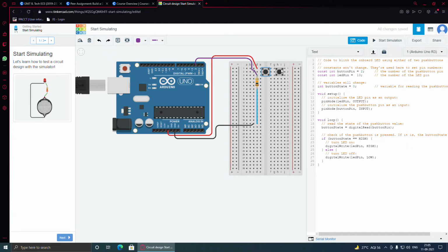If the specified current rating is exceeded, and the component is operated at values exceeding its rating, then it will die prematurely. So most of the components that we use in IoT devices, like LEDs and switches, have quite a low current rating, of the order of a few milliamps.